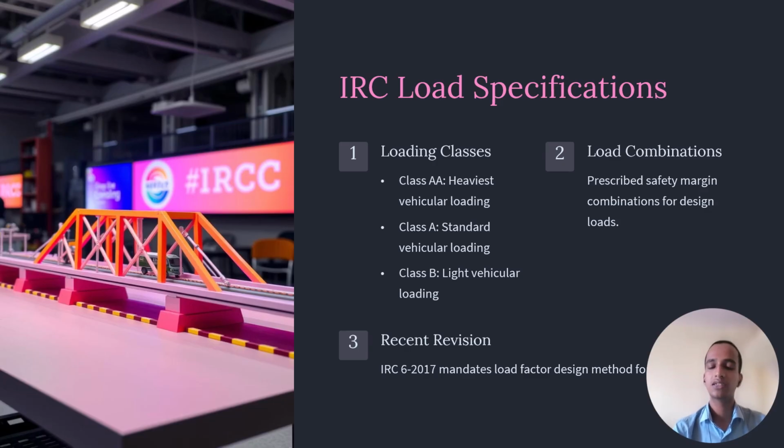Second is the load combination. For load combinations, generally we take 1.5 into dead load plus live load plus wind load, but it may change according to the specifications. Also, revisions have been given in the Indian Road Congress code in 2017, and they have made it compulsory for us to include a safety factor.